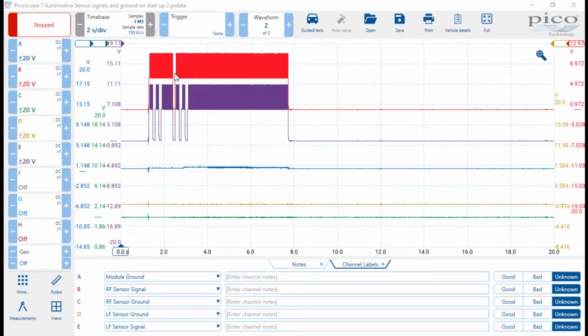The right front appears to come on. This is me cranking the car to start it up. You can see here that the red one, the right one, is not setting any code, so this would be a normal voltage pattern. You can definitely see that the voltage pattern is different on the sensor that's setting the codes. So what I'm going to do is zoom in here and take a look. Obviously, the computer's seeing something here it didn't like. Tested it a couple of times, and then it literally turned the light on, set the code.